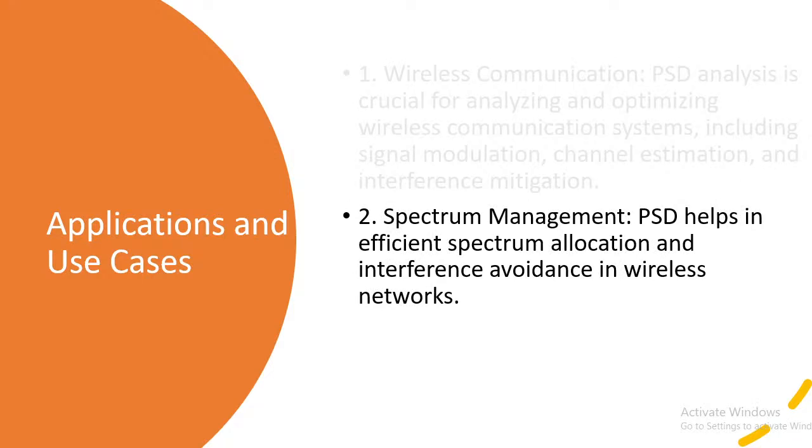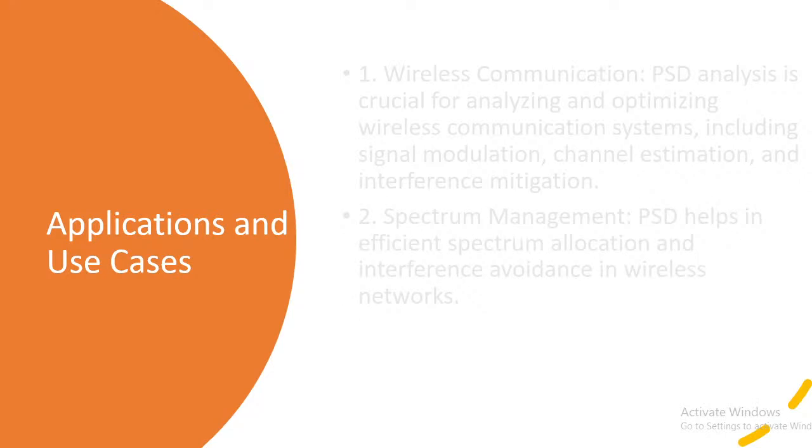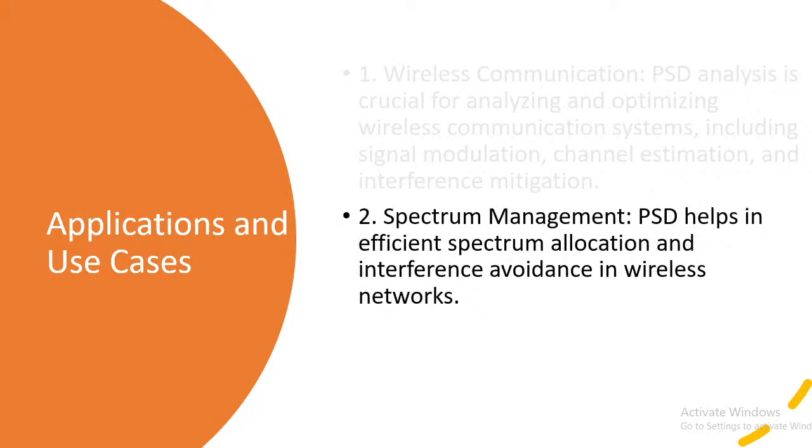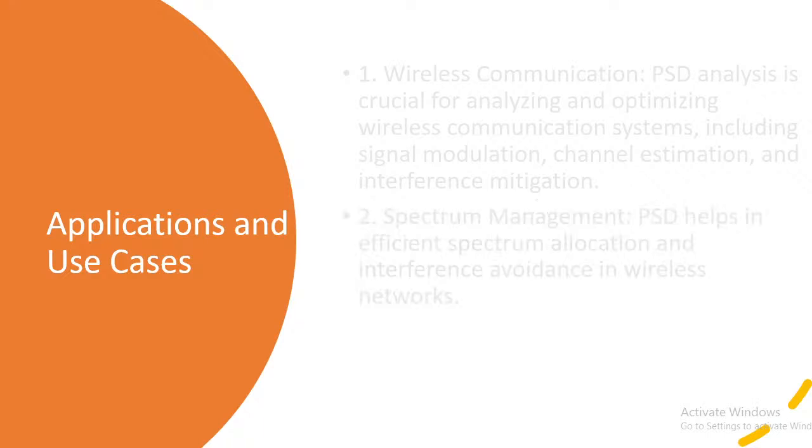The second application is spectrum management. PSD helps in efficient spectrum allocation because we know which frequency components contain maximum energy. We allocate those frequency components and avoid other frequency components for that signal. That helps in spectrum allocation and avoiding interference in wireless networks.